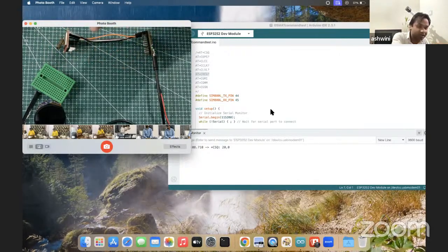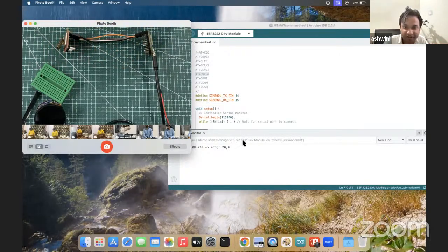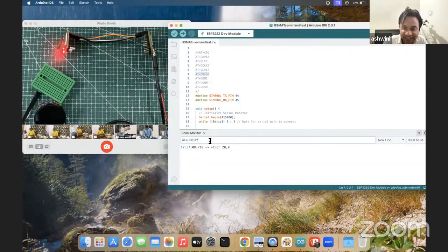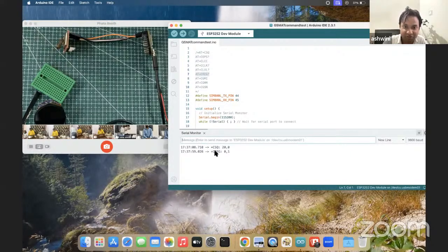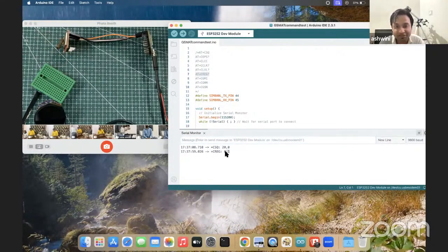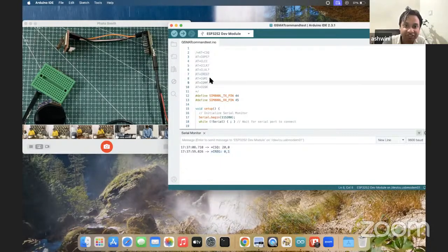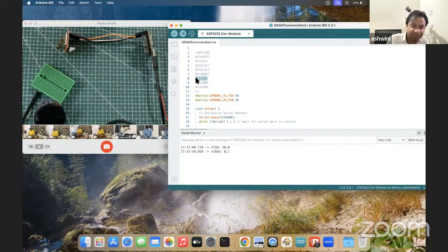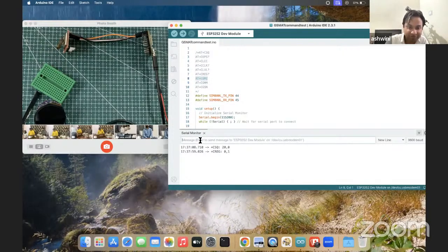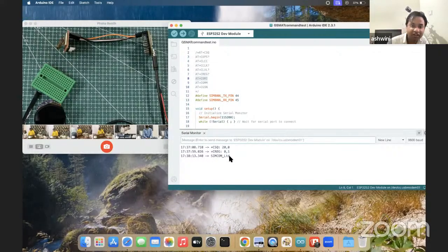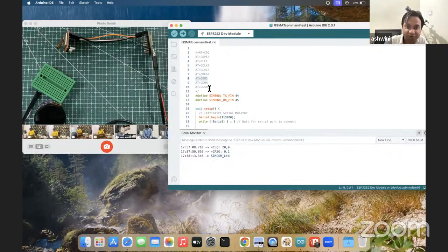I am going to check whether it is connected to the network or not. What is the network status? Using AT+CREG, we will get the network status. 01 means it is connected to the network. Now I am going to check the model number of the SIMCOM using this AT command.